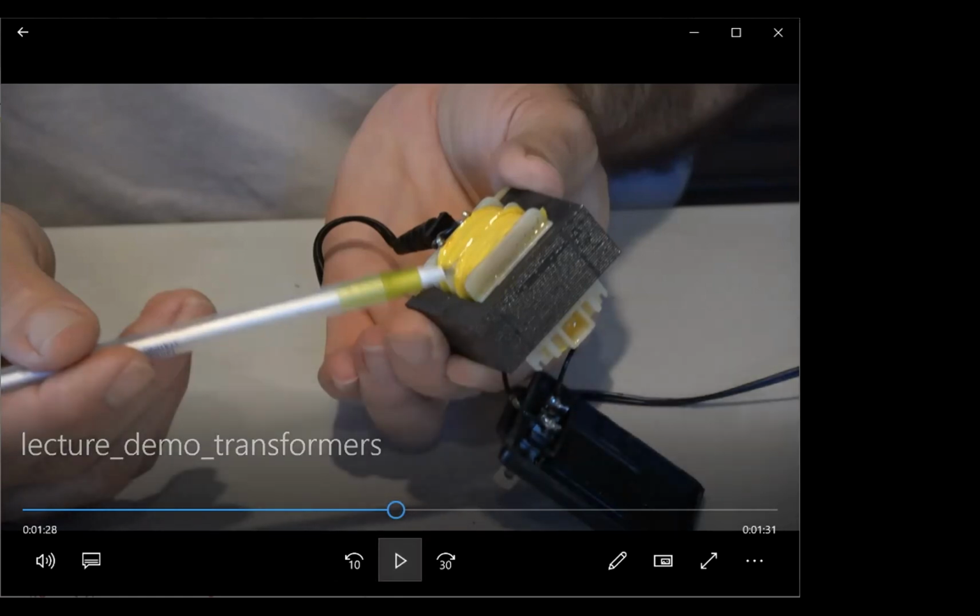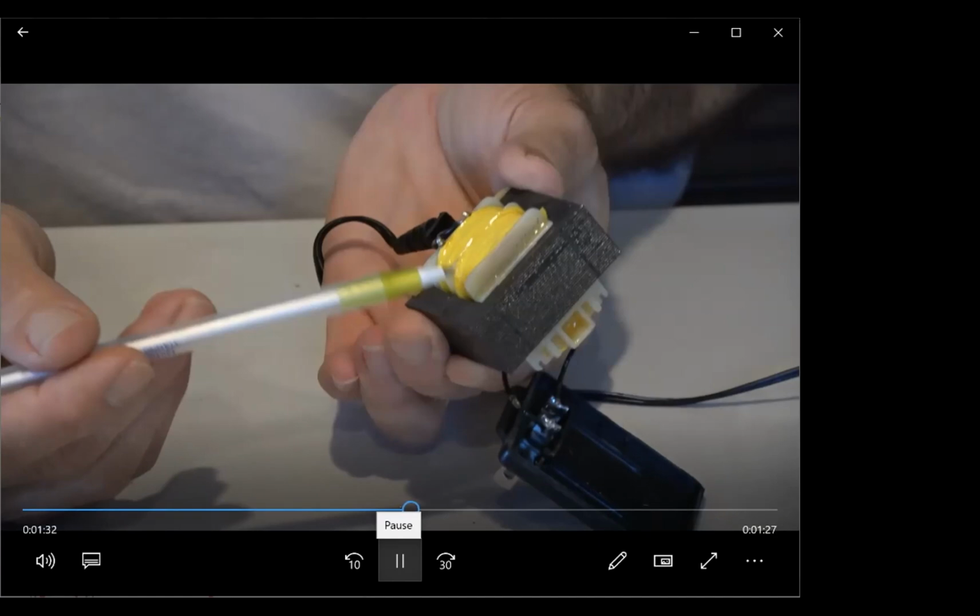What's missing? What are we going to get out of this box? Yeah, it's missing the rectifier. We're going to get AC out, just at a different voltage than what went in. There's nothing here to change it to DC. Did you spot what's missing?